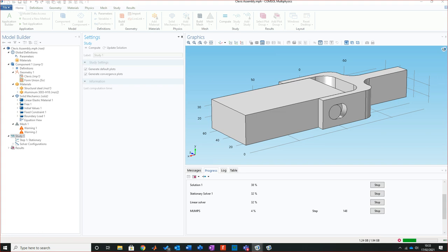We have hardened geometry that goes up the back of a human, and each piece of geometry acts like a spinal section. Each spinal segment then has hyperelastic materials that connect them together, almost a spinal column. We've had to model the two together, restricting it with an actuation.